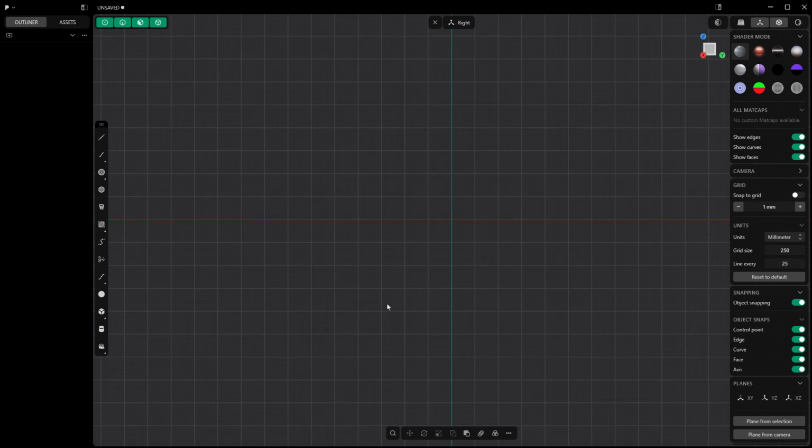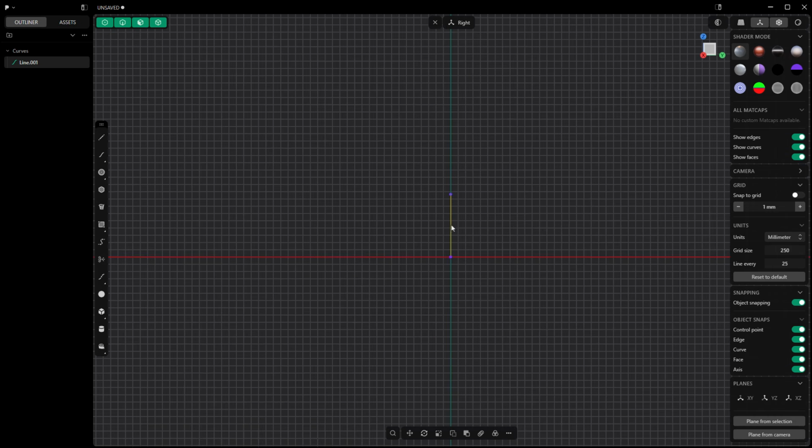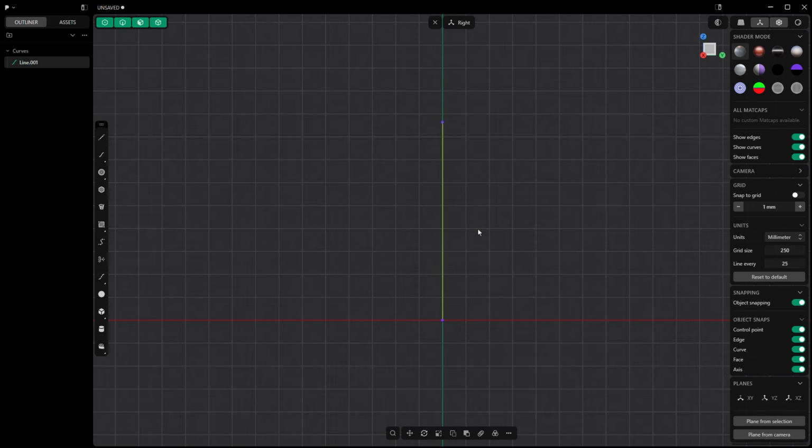But I'm going to click where everything is and only use the shortcuts if needed. We're going to start with a line. We start at the origin and begin to drag up. Then we hit the Tab key, which will go over to our dimension. Most motorcycle rims, at least on sport bikes and supermotos, and a vast majority of bikes, will have a 17-inch rim by default. So we're going to enter 17. That's the diameter, so we do divided by 2, then hit space, type in inch, and enter. What we've done is create the radius, because we did 17 divided by 2.